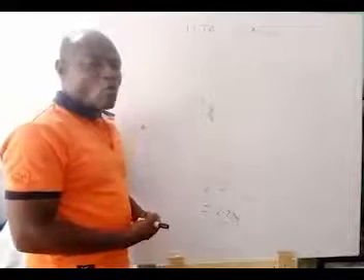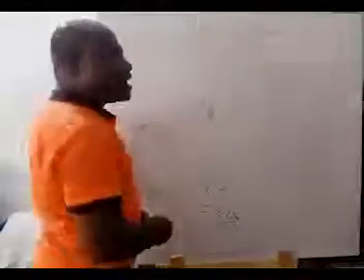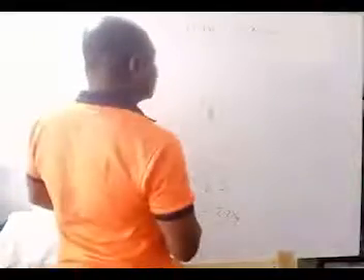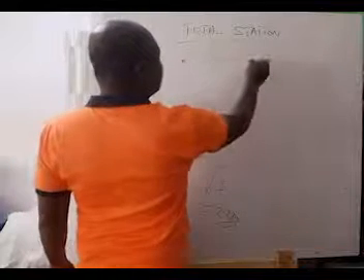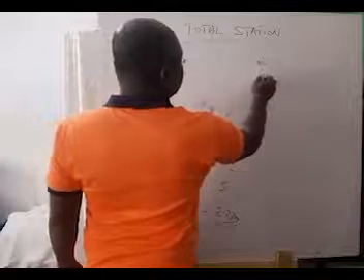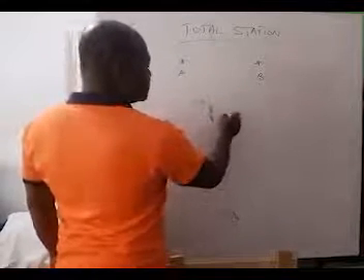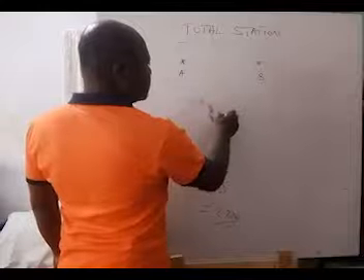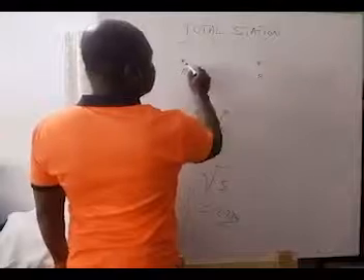In that case, you have to go by what we call resection. How does that resection work? So you have one point on this wall, another point on this wall. Let's say A and then B. You set the instrument somewhere, maybe at C. Then you input these two coordinates because you know the coordinates, northing and easting.